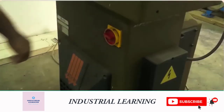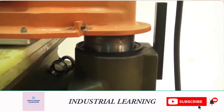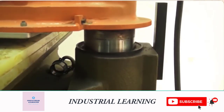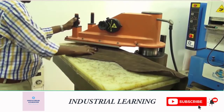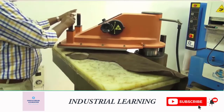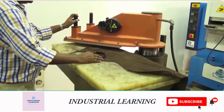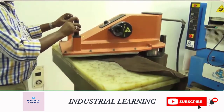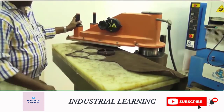This is a die cutting machine. The operator switches on the machine. The pneumatically controlled cutting head rises up. The operator keeps the die and clicks it and cuts the leather in the shape of the die. Now you can see that he has placed the die onto the top of the leather, clicks it, and he has taken out the shape.